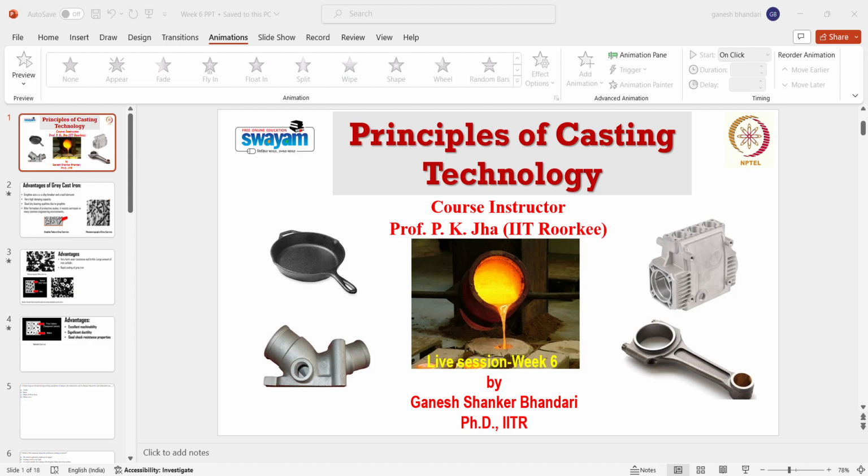During that annealing process, the iron carbide present in the structure of white cast iron, most of the graphite in white cast iron being mainly present as carbide, is going to break down into ferrite and free carbon, which we term tempered carbon. As we can see in this micrograph, there is tempered carbon present.